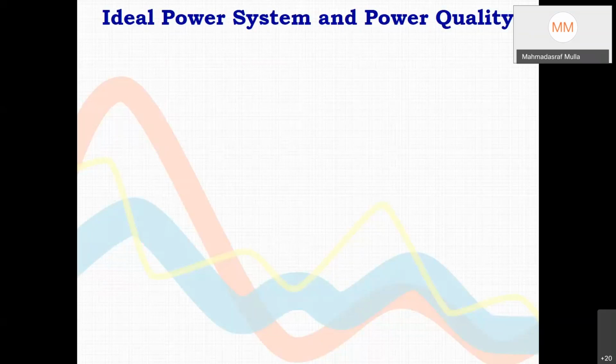Okay, so these are the few points. We can say the power quality problem is solved when voltage and current are sine and in phase, irrespective of anything. You may be connecting a rectifier, a motor drive, anything. All the load should draw a pure sine current in phase with the supply voltage. Then we can say it is the optimum we can achieve while transmitting power from an AC source to the load.